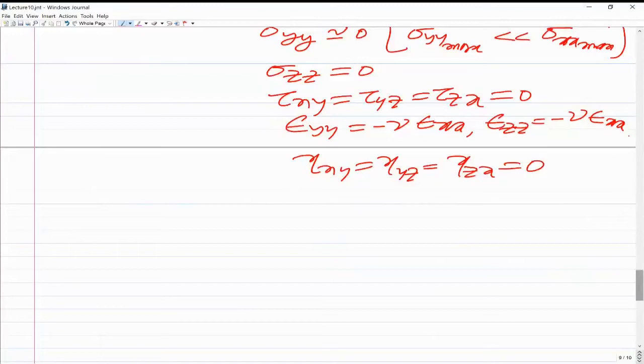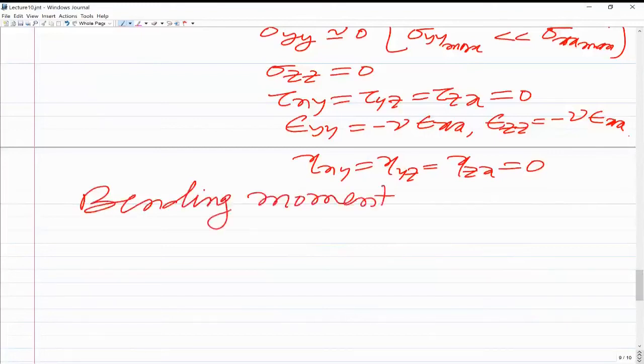Now, earlier when I had discussed the weak form and the integral functional, I had taken that fourth order differential equation directly. So let me derive that, how to get the differential equation for the beam. The weak form and integral functional we had already done, so I will not be repeating that. Before I go further, let me define the bending moment. I am going to denote the bending moment as the moment about the z axis.